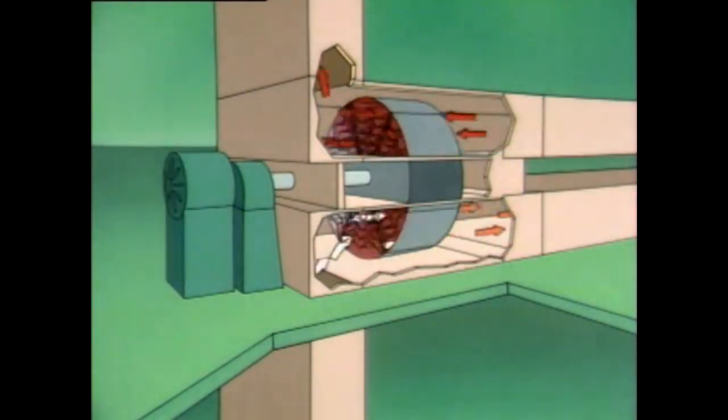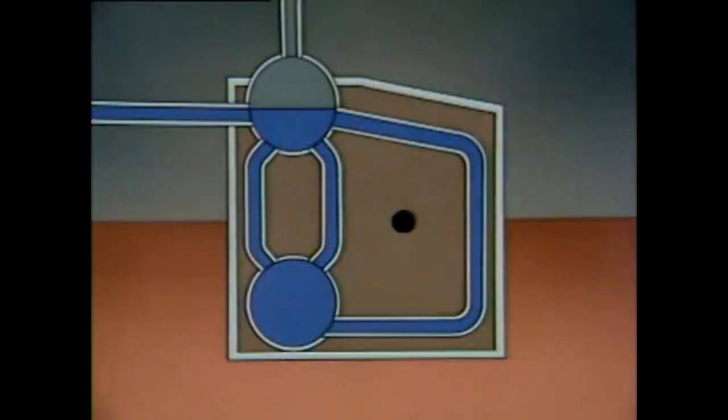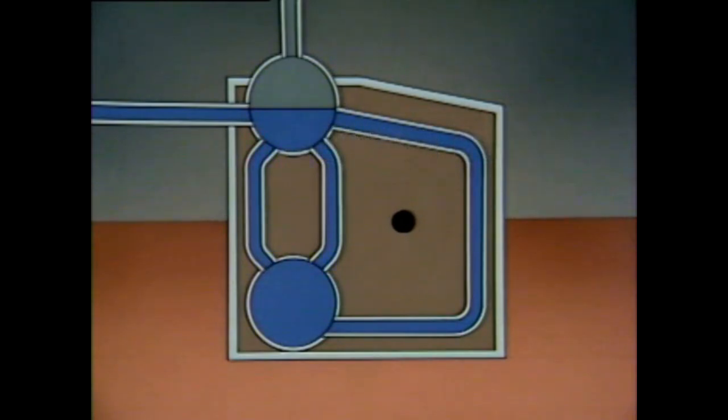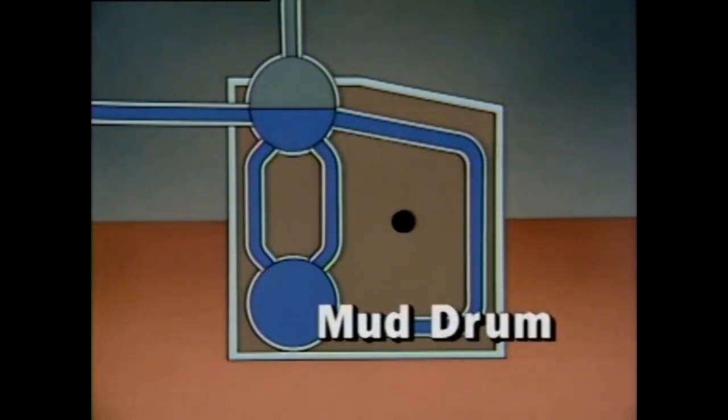boiler operates more efficiently. For a boiler to produce steam, water has to flow through the boiler properly. One way to provide water flow in a boiler is by a process called natural circulation. This simplified water tube boiler illustrates how it works. The boiler has two drums. The upper drum is sometimes called a steam drum, and the lower drum is often called a mud drum.